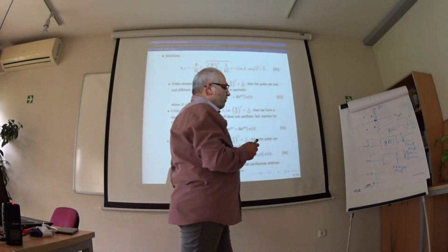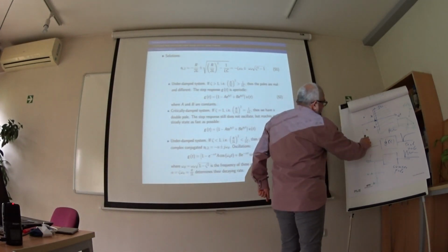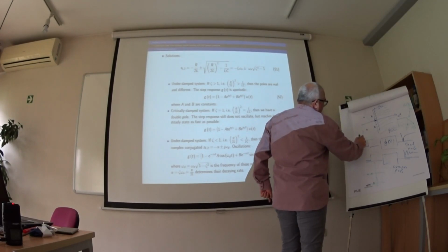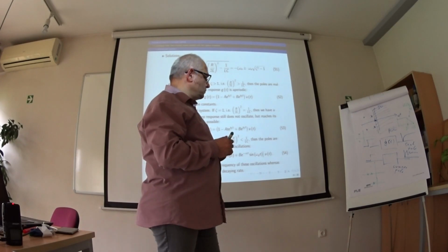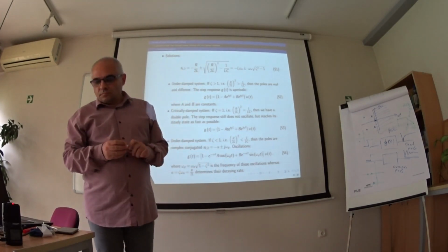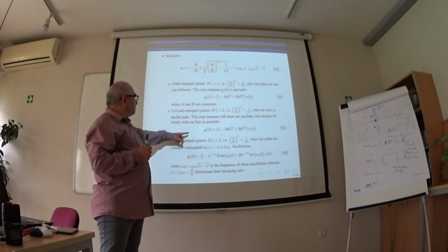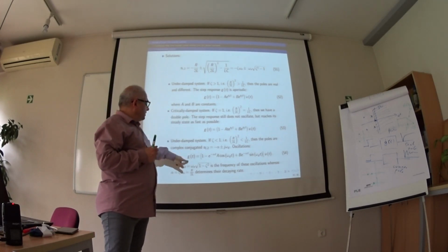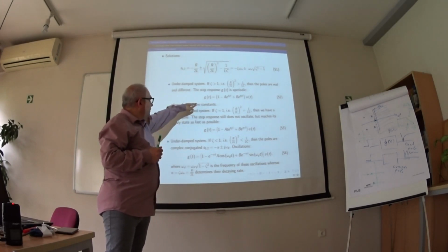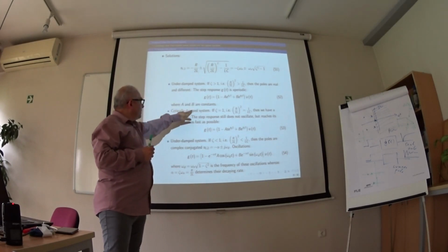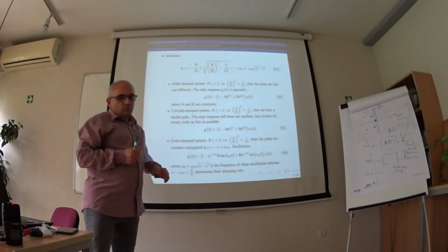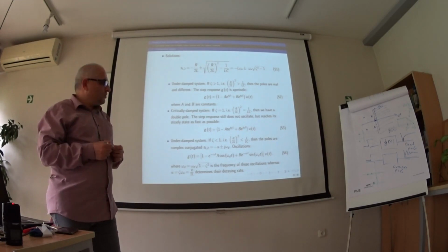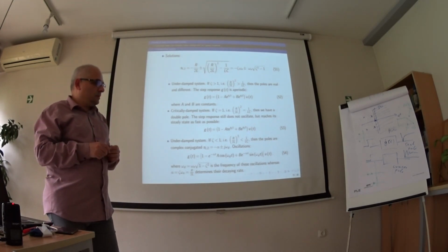When we have an underdamped system, we have a pair of complex conjugate poles. The step response in such a situation oscillates. Here we don't have oscillation. When we have the critically damped system, the output still doesn't oscillate, but it reaches the steady state as fast as possible.